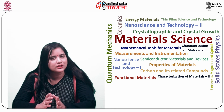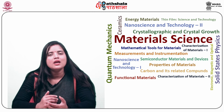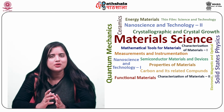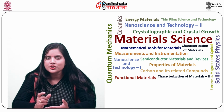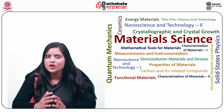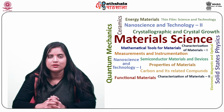The van der Pauw technique is employed to determine the resistivity and Hall coefficient of a material. It can accurately measure the properties of a sample having any shape, if the sample is a two-dimensional solid, that is, without holes, and the electrodes are positioned on its perimeter. It uses 4-point probes positioned around the perimeter of the sample rather than in a straight line.